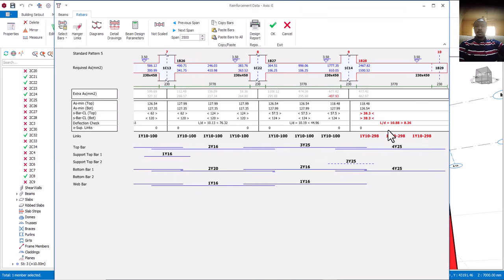Okay, but here is still failing. So when you have adjusted it like this and you have done what you expect to do, and yet deflection is still failing, it's failing at deflection and all of this, you automatically know that the beam depth is not sufficient. So how do we go about that? We now go and increase the depth of this beam.